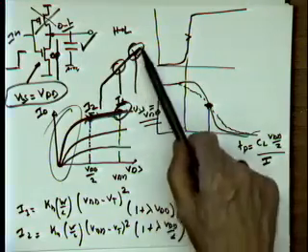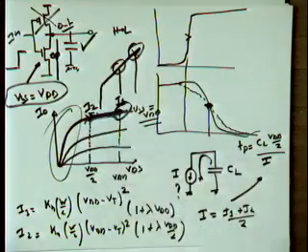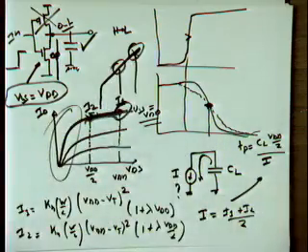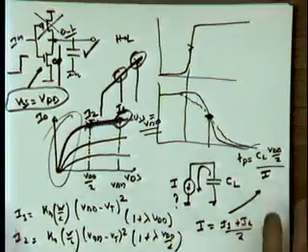So now you have to look at the current. You're looking really at the charge, right? I have a certain amount of charge that I want to remove, and the current basically helps me to remove that charge, right? So that's why you have to look at the whole interval, not just at the midpoint. It's a transient. It's not a DC characteristic. Okay? So that's approach number one.